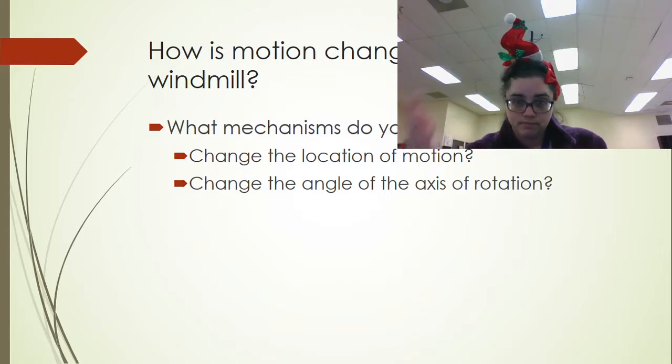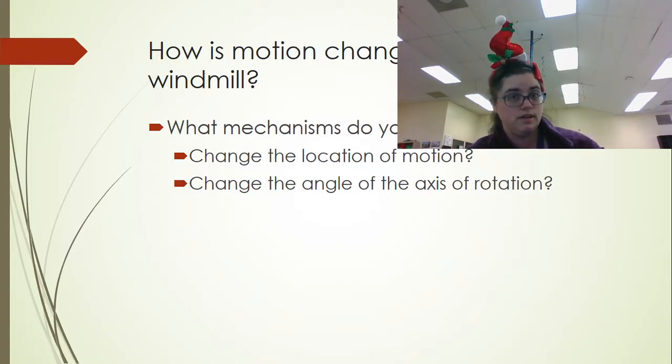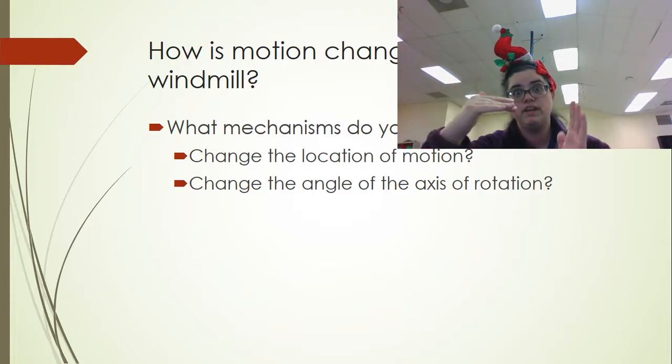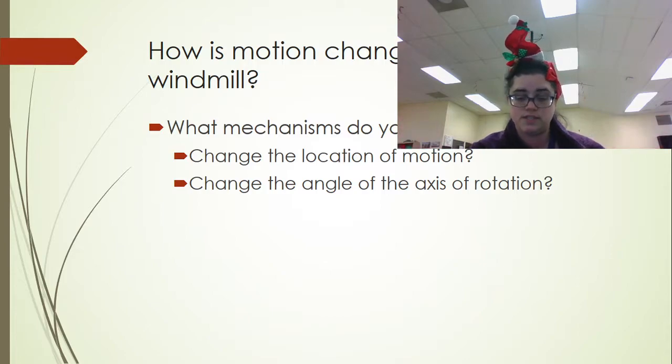They only do a maximum, I think, kind of like that. So that's another option that I've heard people mention, but it's not something that's going to help us building with our VEX parts. There are special universal joints with the ability to go 90 degrees. Or you can put 2 together. Again, you're creating more moving parts for yourself.